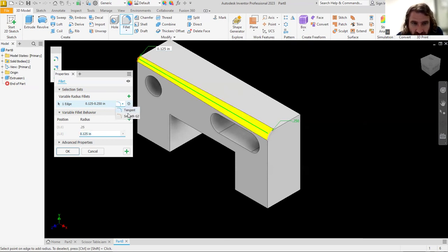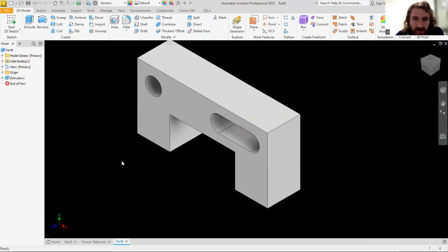There are different ways to do that, and we can make either tangent or smooth G2. There's no option here for the inverted with a variable radius fillet. A variable just means it changes, right? It starts as one size dimension fillet, the 0.25, and it ends as another sizing. So let me hit cancel real quick.